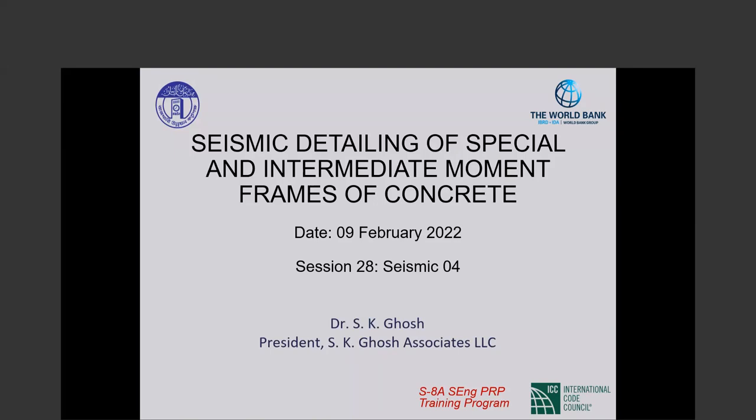If you have design category B, your moment frame can be an ordinary moment frame. And then you go with the non-seismic detailing that we discussed on an earlier day. However, for ordinary moment frames assigned to design category B, ACI 318-08 section 21.2 has a couple of requirements.